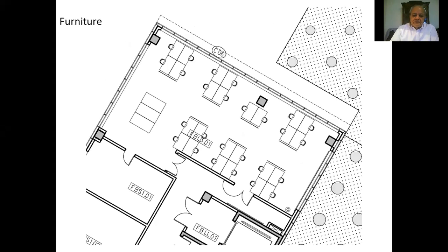The second plan, you see, we are using the same architectural plan that we developed in the beginning. That's why when we use AutoCAD or any system, we need to have layers. We don't put everything on the same layer. We have a layer for center lines, a layer for columns, a layer for doors, a layer for windows, so we can turn these layers on and off easily.